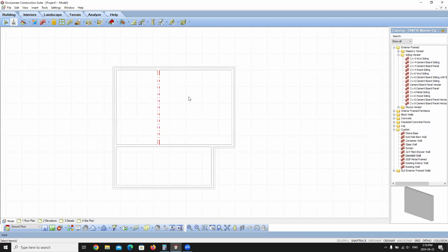So at this point in time, we have now created and established the existing plan. You may want to transfer this to a working drawing sheet before inserting any new walls to illustrate the existing plan before any alterations. You can add dimensions and notes as required. You can also add in doors and windows again to this plan to show where the existing windows and doors are going to be placed.